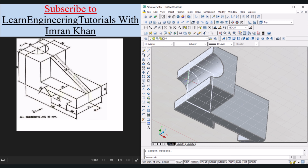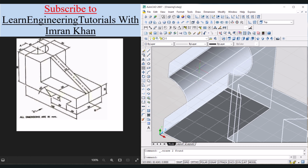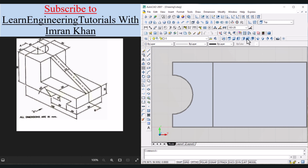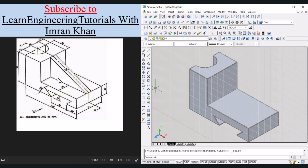Now we have to remove these items. Click on this rectangle, click on this semicircle alone, press delete, and we can see that this object is now a single entity. Click on top view, click on front view, click on isometric view, and now in this view we have to draw this triangle in the front view. So front view is already selected.